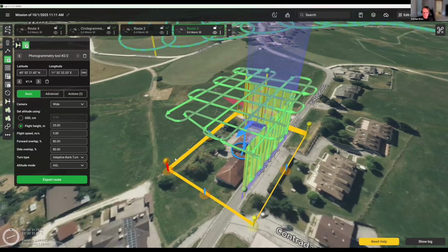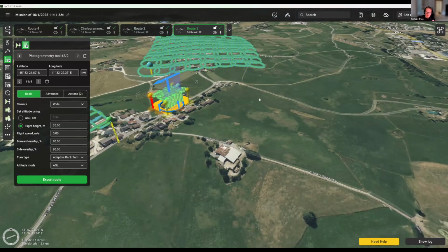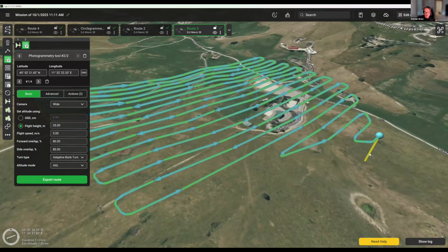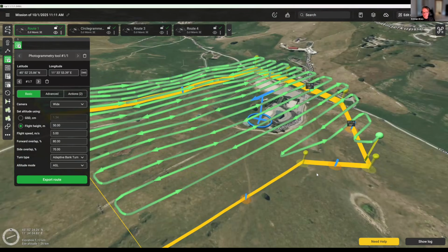The only thing you can do with DJI drones, and I think a lot of people don't really know about this: let's say you launch your drone on a photogrammetry mission and you realize the drone is flying a bit too slow, or maybe you want to speed up some parts of it, or you see some obstacles coming up and you want to slow it down a bit. While the drone is on automatic mission, you can use the throttle stick of the RC, and this will slow the drone down or speed the drone up. This 100% I know it works.